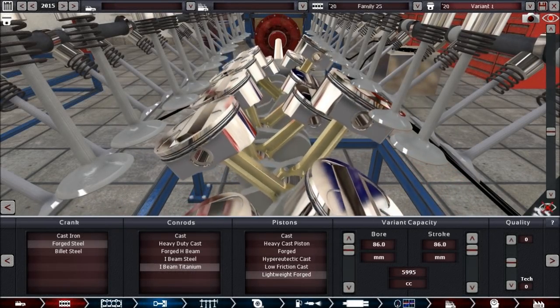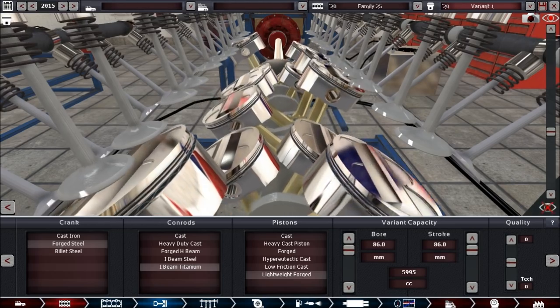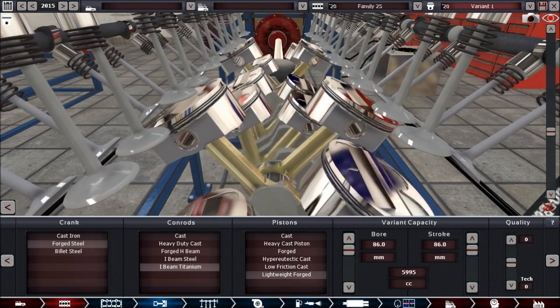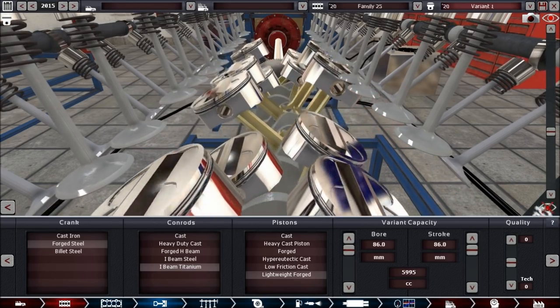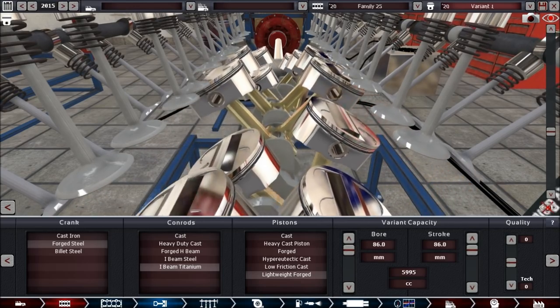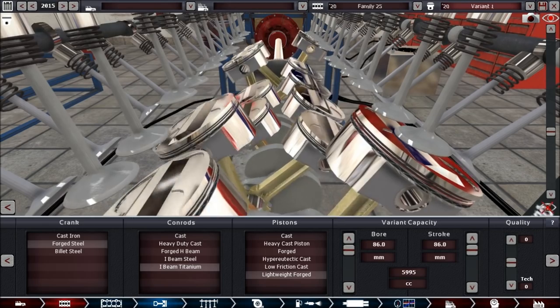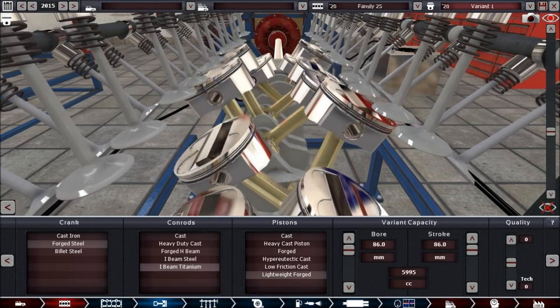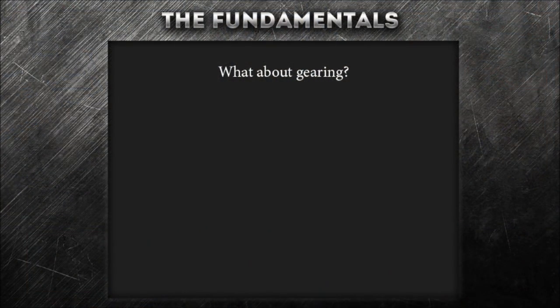Not quite. Torque, as in the amount of work produced per combustion cycle and not the static force and lever, becomes an interesting measure when we take into account gearing. So what about gearing? Let us consider having a standard manual gearbox with fixed gear ratios fitted in the car and work out the acceleration from there.